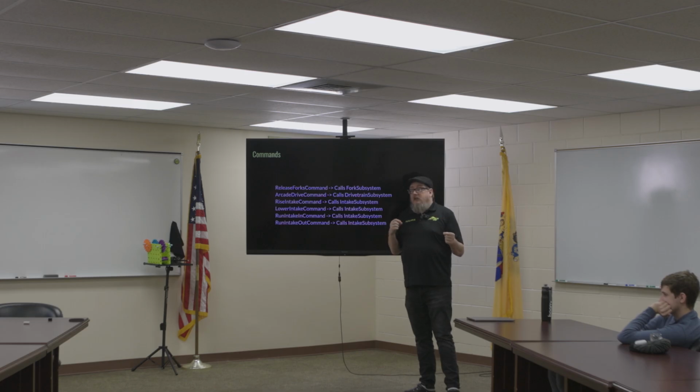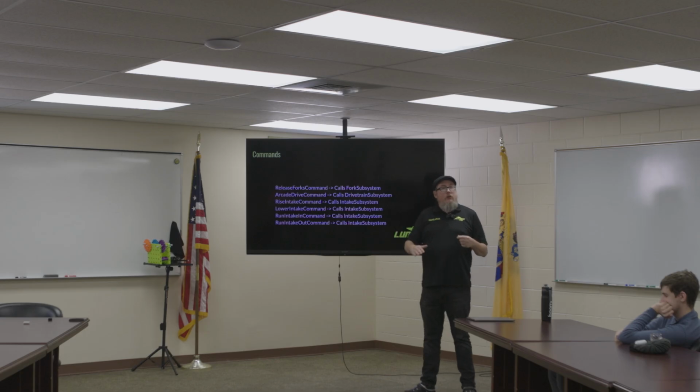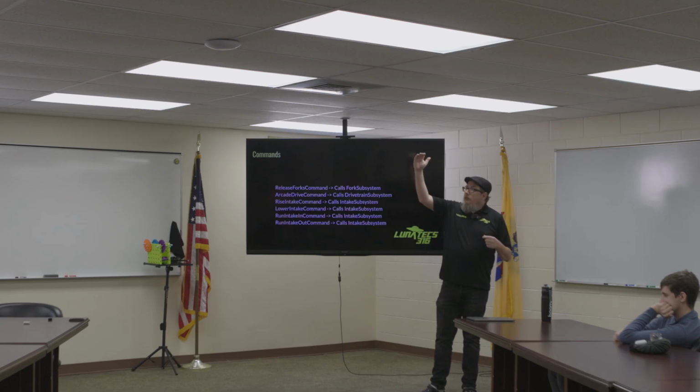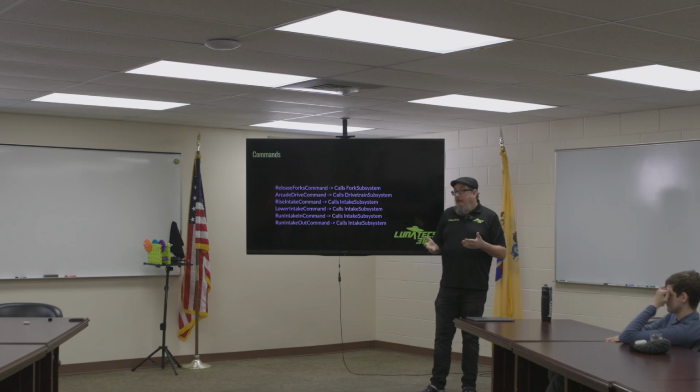Does that make sense? So if we find a problem with one of our commands, we just have to change that command and it fixes it for auto, but it also fixes it for teleop. So when we took the elevator up to the proper height to deliver the Coral this year, if that elevator wasn't getting to that proper height, we changed one command, and we fixed it in that command, and then it fixed it both for auto and for teleop. Does that make sense? And this is how we can reuse code.